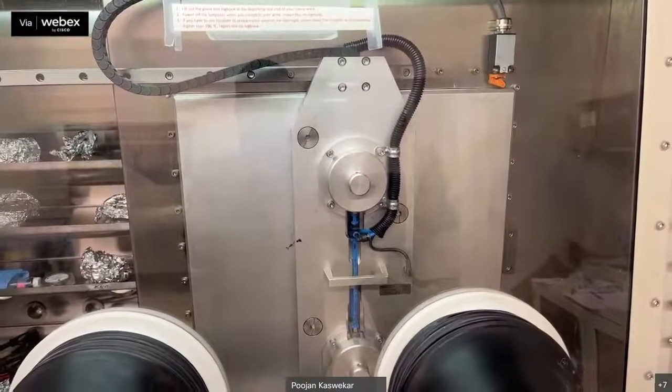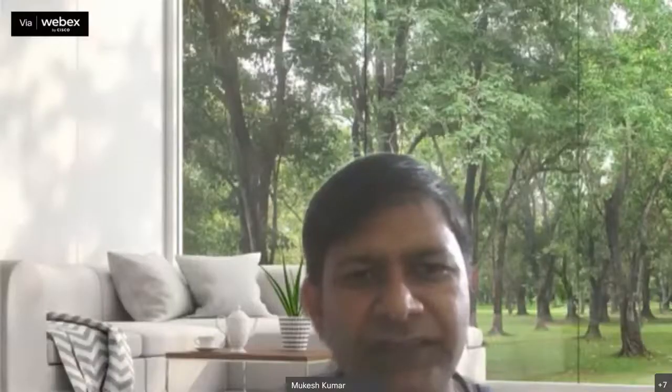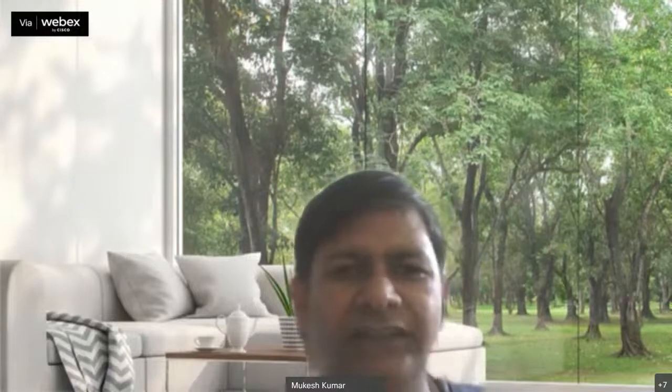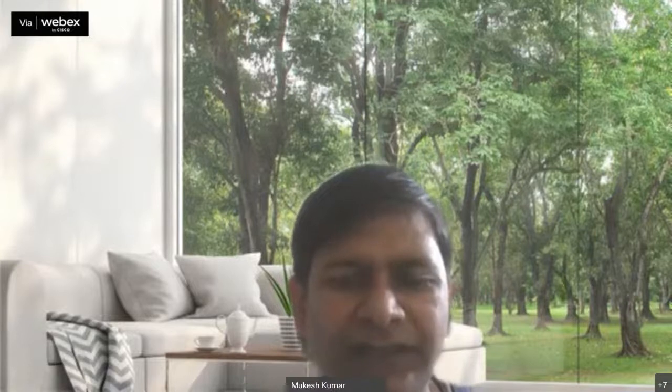Yeah, so this one, you see, is the thermal evaporator. You just insert your 2 hands, and it has a door, so it can slide. You put your final device inside with the physical mask on, and you have a few openings there. Through the openings in the physical mask, the metal is getting deposited. So that is the final device where you can prepare that. Generally we keep the two things separate, one is chemical processing, and another one is physical vapor deposition, where we deposit the final metal contact. So these two chambers are generally separate.